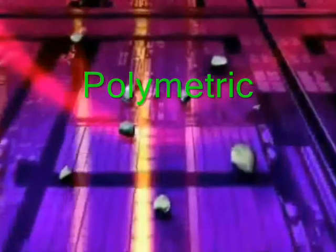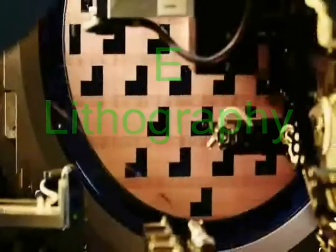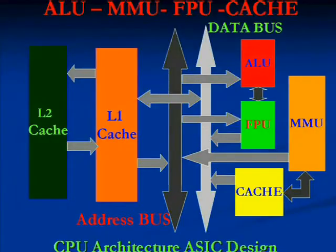In addition, the chemical effect of ionizing radiation also limits reliable resolution to about 30 nanometers, which is also achievable using current state-of-the-art immersion lithography. Hard mask materials and multiple patterns are required.